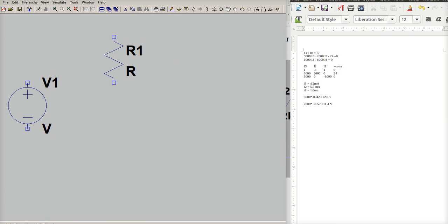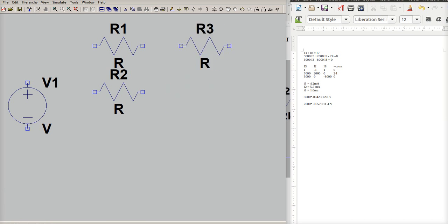And what you notice is my resistors in my handout are horizontal and these are vertical. In a lot of programs, Control R is your rotate. That's a shortcut for rotate a part. So I'm going to rotate this one. It's going to follow my mouse around. I'm going to click to put it where I want it. I need 2 of them, one above the other. So I'm going to click that one. And then I need a 3rd resistor to make it look like what we had in the first drawing. So I'm going to click there. I don't need a 4th one, so I'm going to hit the escape key.